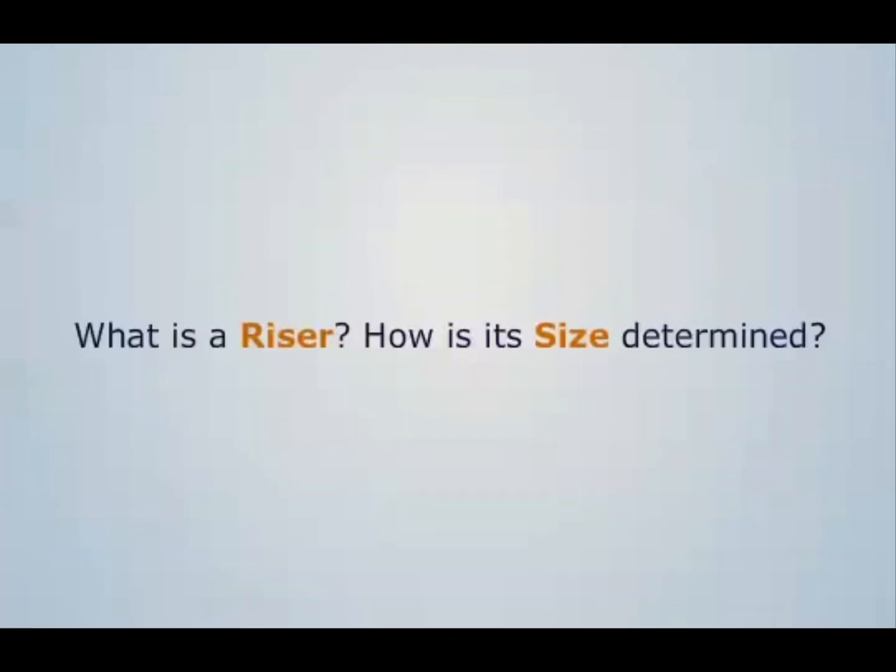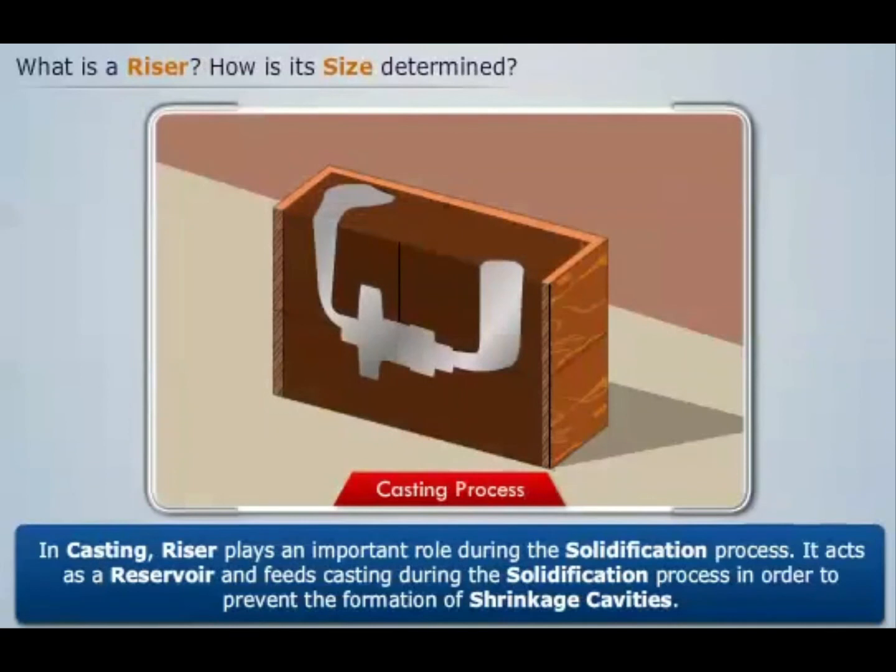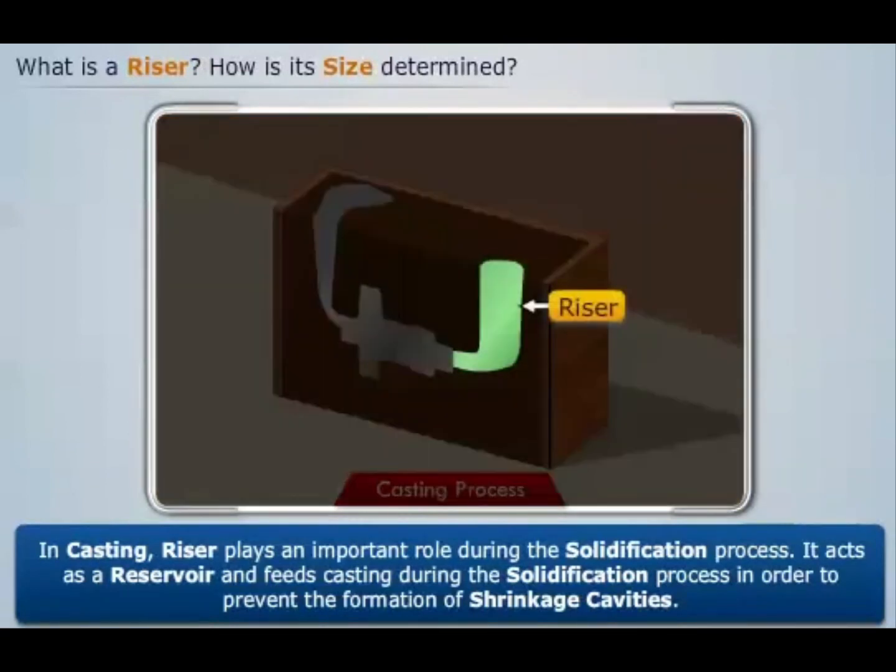How is its size determined? In casting, the riser plays an important role during the solidification process. It acts as a reservoir and feeds the casting during solidification in order to prevent the formation of shrinkage cavities.